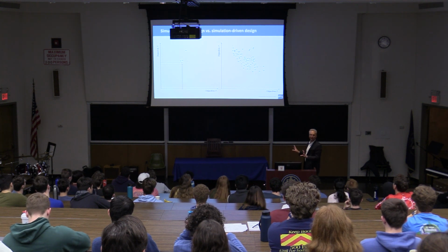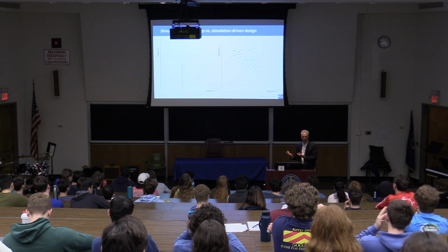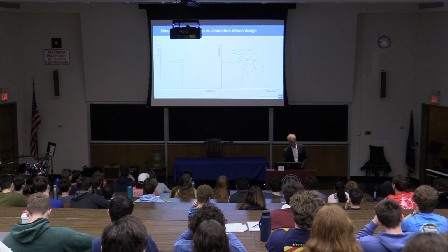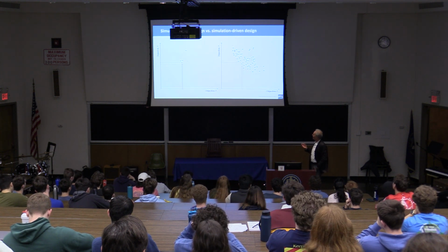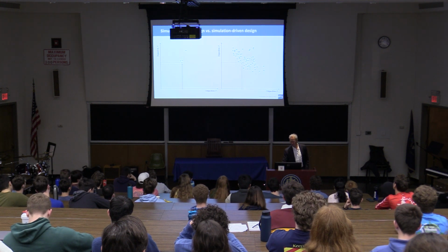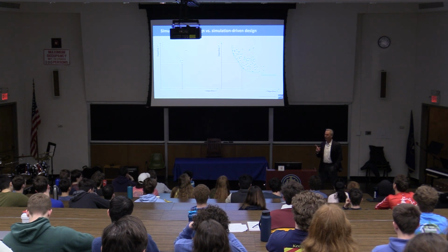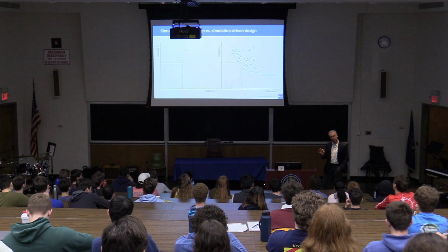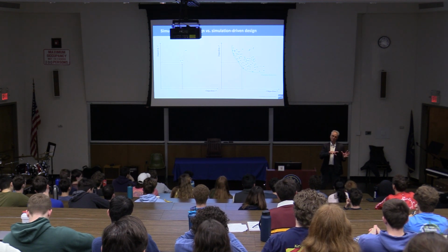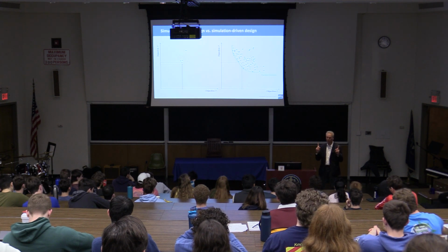You have a lot of variants to choose from. If you analyze dozens or even hundreds of variants, you can understand what is actually the cause and effect of certain things. And then you can choose a new design based on what is called Pareto optimal, meaning that among those different objectives, you have designs that cannot be improved with regard to one objective without actually making another objective worse. This is the definition of a Pareto frontier, a very important concept.